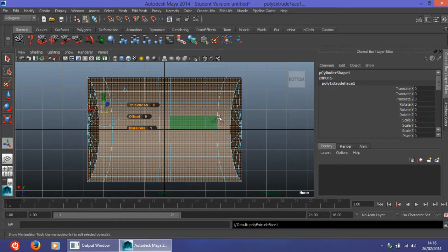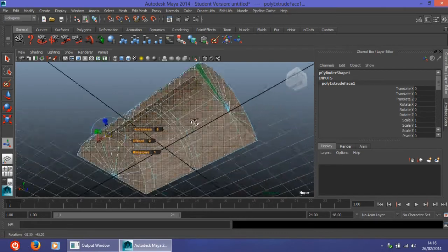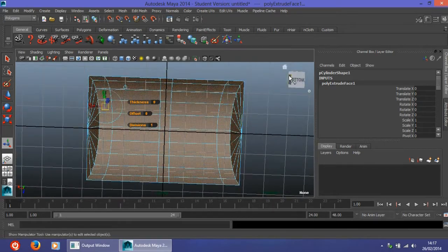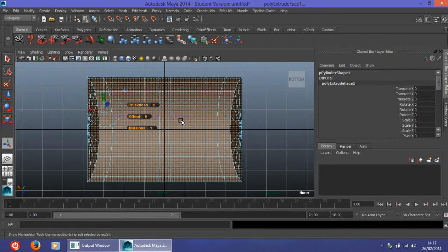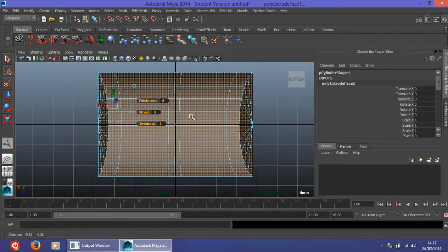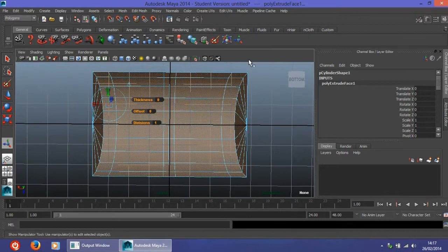Therefore we now have, for example, duplicate faces right here, although we are not seeing them, but they are there, and if we do not cater for them or move them so that we know that we have other faces, that will create some problems later on. So keep the extrusion selected because it is very important.